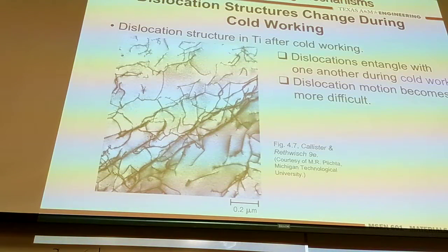However, those strings are not aligned perfectly so that you can push through. Because you have a lot of grains along different directions, the dislocations are not specifically aligned. After extreme cold work, you have a lot of dislocations, just like threads mixed together. So you form an entangled structure, like a knot, and they cannot move.